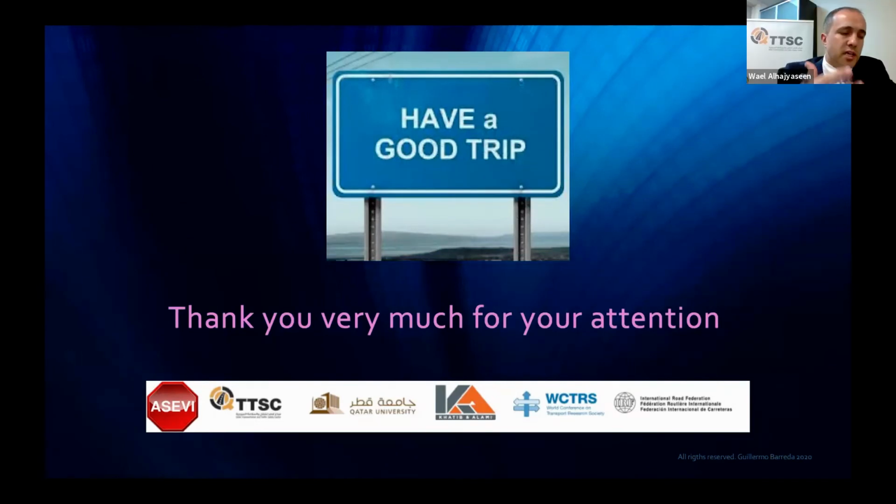Yes, but this raises an important question: speed limits are not usually followed by drivers. So you need to design your tunnel in a self-explanatory way where it directs drivers to reduce their speed. From my experience in Japan, for example, there are very different types of road markings, lane markings, separation markings that make the driver perceive a narrowing of the lane once he enters, and there's a kind of default reduction of speed by drivers due to this marking system inside the tunnel. However, when you have large tunnels, like some examples from Qatar with 3.65-meter lanes that continue straight from the straight section into the tunnel, it's very difficult, even if you reduce the speed limit, to observe a reduction in speed by drivers.